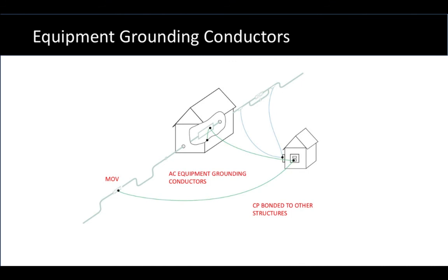Or in the center in the building, there could be electrical equipment in that building that must require power and therefore have a ground. The ground is there for protection for personnel. It allows a fault to flow on the ground, if it's solid and continuous and able to handle fault current, and it allows the breaker to operate. However, as installed on a cathodically protected pipeline, these grounds also cause a short for CP.